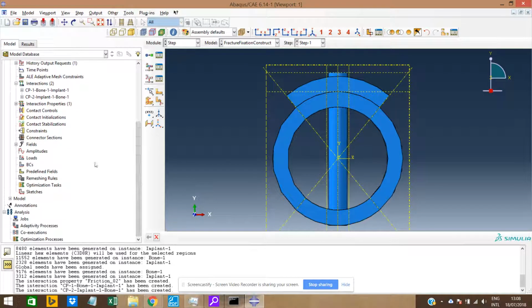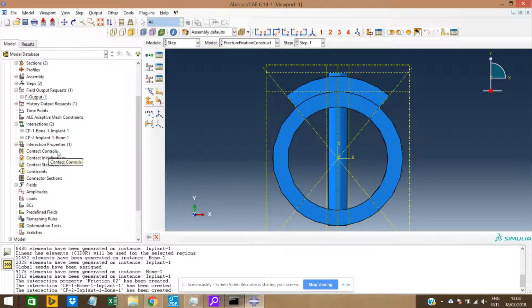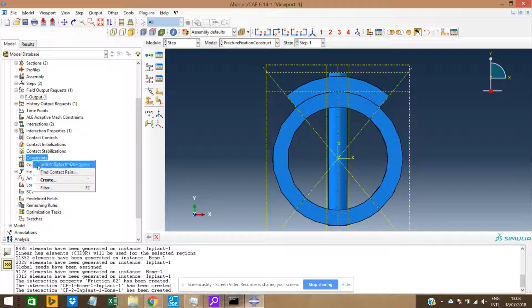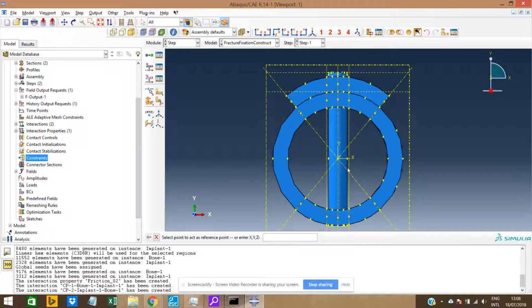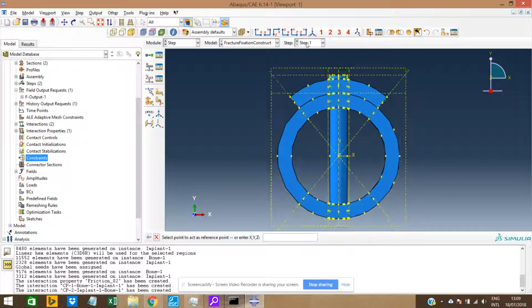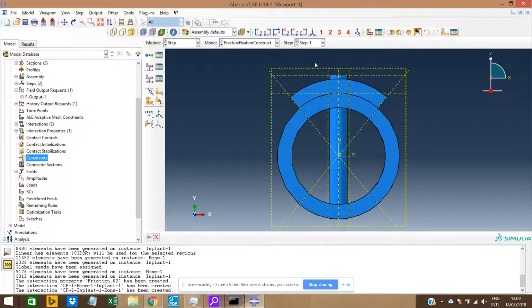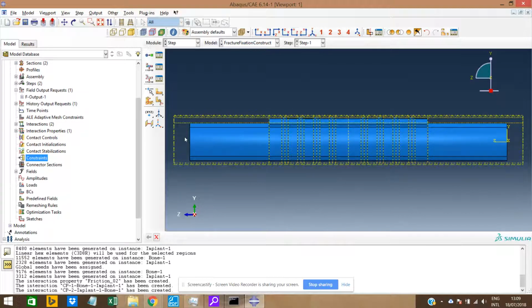Basically, everything should be done now. No. Of course, I need to apply some loading, otherwise nothing's happening. Some loading to these, and normally also some boundary conditions. But to apply this loading, I do the following. So this part is also tricky if you've never done it before. I want to create a moment. Let me first explain what I want to do. I want to create a moment around this so that the bone is in pure bending.